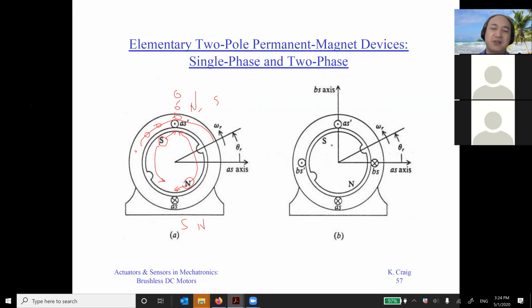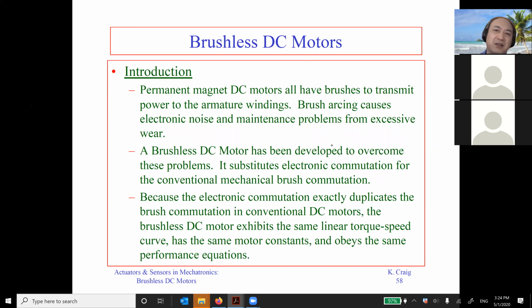When you have alignment, your magnetic reluctance is minimal. So this is something we want to focus on. BLDC. Okay, BLDC. So what's left now is a rotating magnetic field through the AC excitation current by using a three-phase magnetic field, or you use an arrangement of the density of the coils to have a sinusoidal distributed coils.